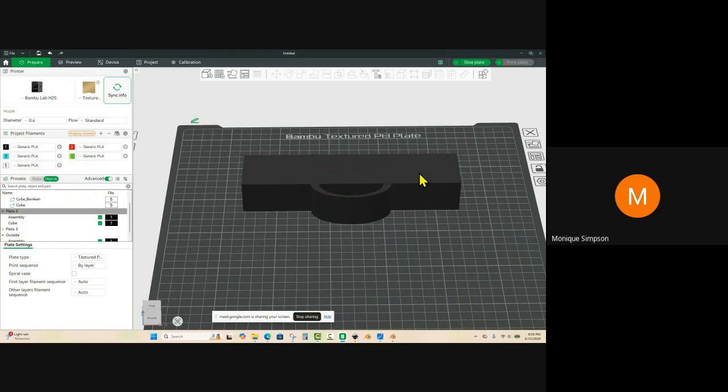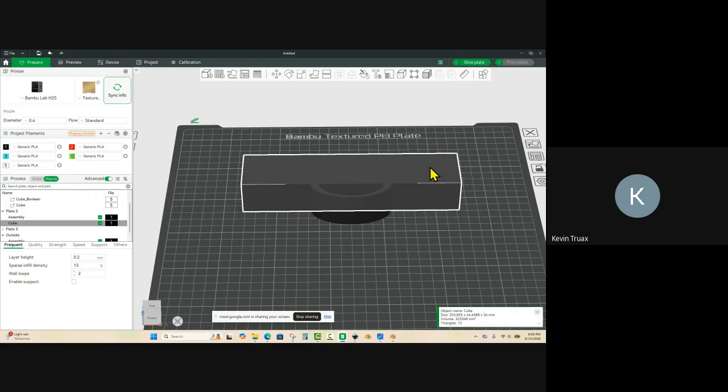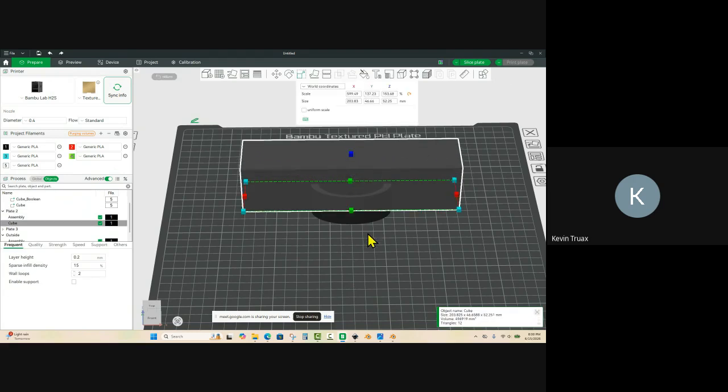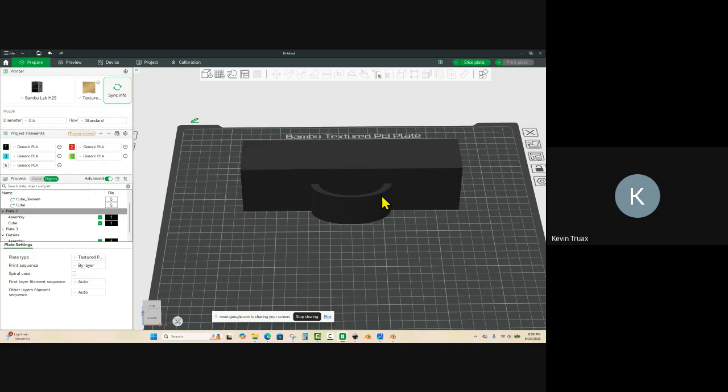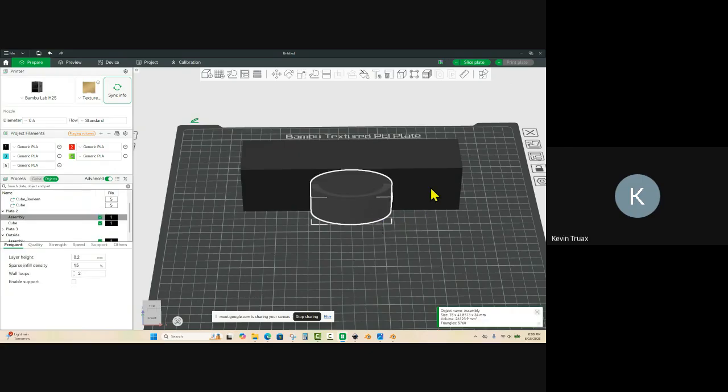So let's go ahead and back up here a little bit, because our cutter is roughly the same height as our handle, and we don't actually want that. Remember I said it's best practice to have it a little bit taller. So we're going to go ahead and raise it up. See there? Now there won't be any conflict whatsoever. So we'll select this one, control click this one.